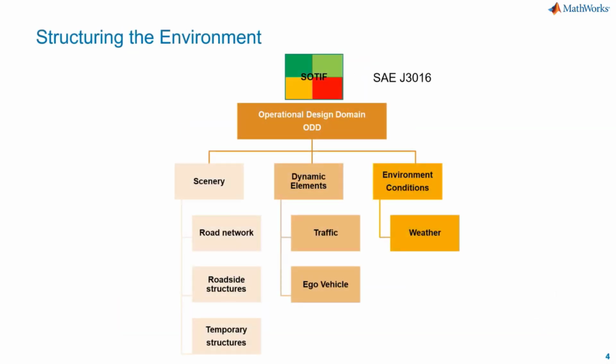So maybe a little bit more details about the SOTIF. It's according to this SAE J3016 standard. In order to follow this SOTIF standard, we should structure the environment, which is called the ODD, short for Operational Design Domain, right? So in this standard, it refers us to different categories to structure the ODD.